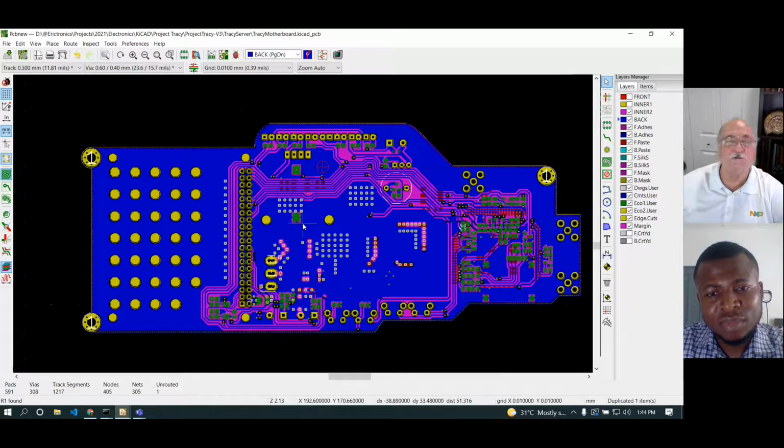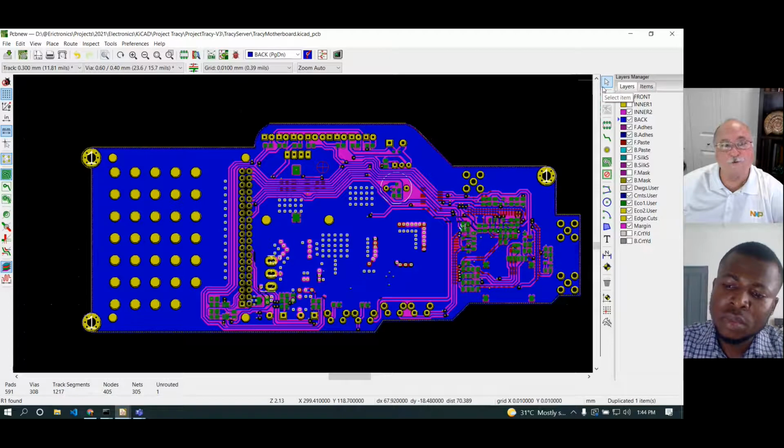The only thing left to check is to make sure that when we have moved from the paired dielectrics between layers 1, 2, and 3, any signals or power routed from 1 or 3 to layer 4 will require ground transition vias to connect to the dielectric between 4 and 3. So this is where the final check would be.